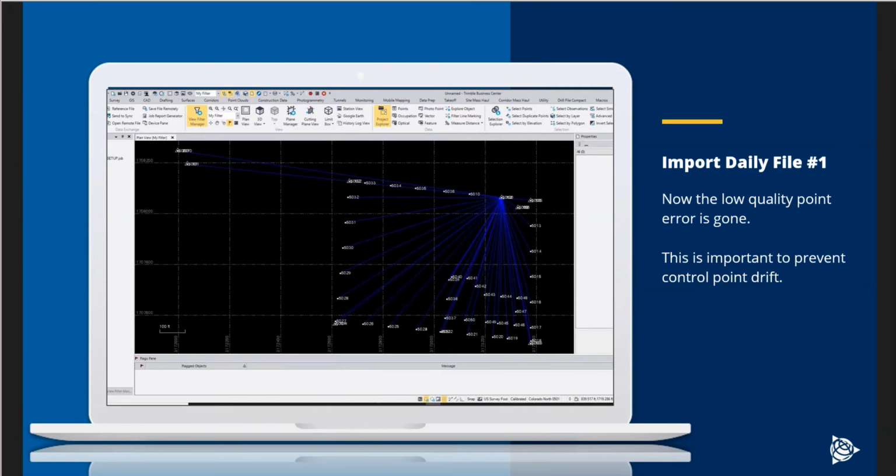On a construction project that goes months and months and months, it can help you prevent what I refer to as control point drift, where you start getting all these multiple values of these base points that are off a rounding error of 100th or less, and you keep going through.